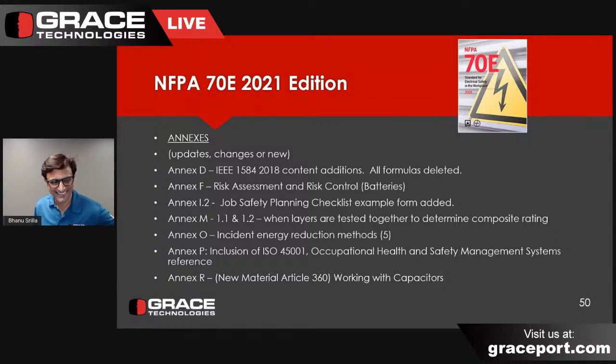I'm doing the calculations, but I don't even have IEEE 1584. And IEEE 1584.1, which I'm going to mention later, I'd say 90% of the electrical engineers doing the studies don't even know that that complementary standard to 1584 exists, and it'll allow you to do a QA/QC check and audit of your report. And then you can tell the client your report's compliant to 1584.1.